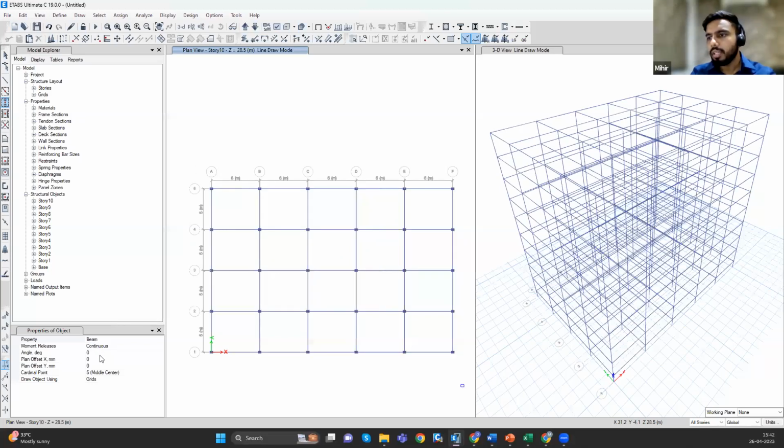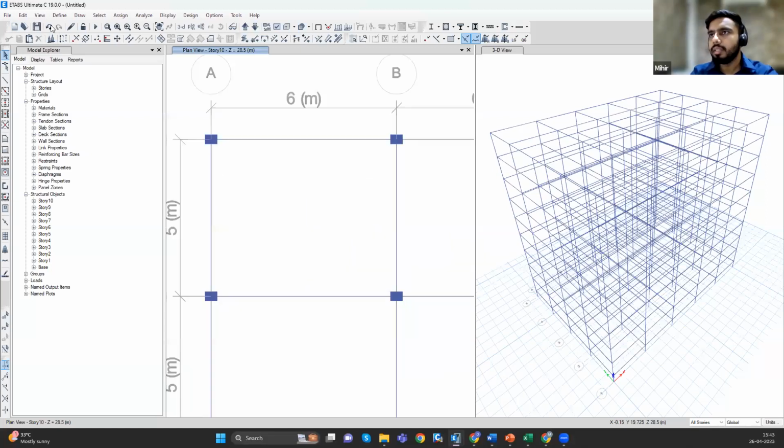One important thing that we missed is that while defining the element or assigning the section, we need to see what type of property is being used. As of now, you can see I am doing it wrong because my column was having symmetric sections for both the directions. So I'll just undo this.